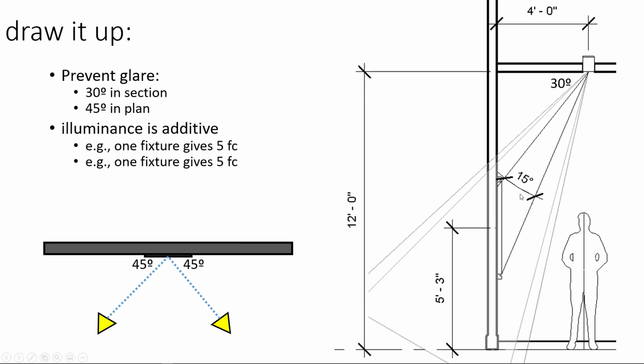Another concept about lighting paintings, and here I've drawn up a diagram of lighting a painting from a recessed can in the ceiling. I've done my calculation of the angle. I know my ceiling height. And I also have to consider that I probably will want 2 light sources on this painting. The problem with one in the center is with a bigger painting, the human being observing the painting may get into the light range. It might cause a shadow. So in a big painting, it's better to have 2 lights on it anyway.